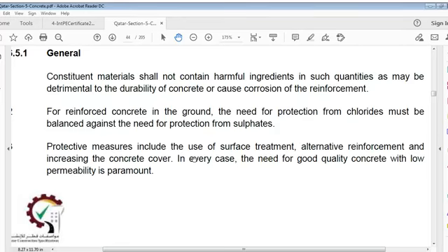So, what do you say? Use of surface treatment. Whatever foundation we lay, it should be protected from the adverse impact of chlorides and sulfates from soil and also from water-soil solution, which carries with it very fine particles and chemicals. So there should be proper surface treatment, which may be called waterproofing in your trade language. Or it is concrete surface protection from soil and from chemicals, and which also should be further protected so that your water protection membrane remains intact.